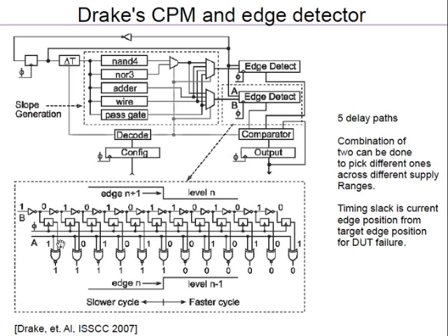And because it's alternating, they are doing this XORing. So the XOR is looking for a transition. Where is the edge out here? After you do the XOR, you see all ones and then 0, and you see that the transition has happened at this point. So you see that the edge has traveled up to that. So this is kind of what is done basically. It's just another critical path monitor, but the technique for measuring the delay is the same. A small variation of inverter versus buffer, and using these XORs to get you the transitions.